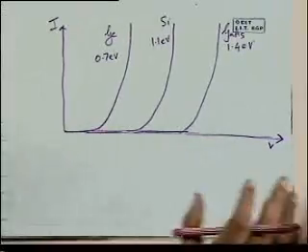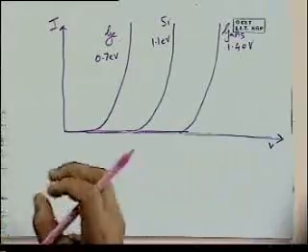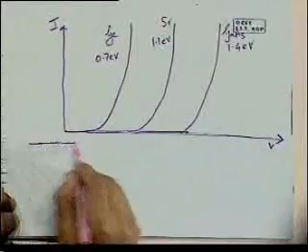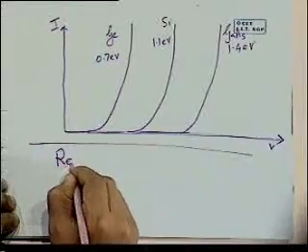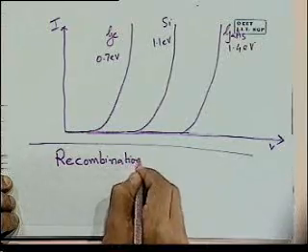So this is what we have written as a term for the current flowing under forward bias conditions that accounts for the diffusion of species under the lowered barrier. But there's another current term also that is related to recombination within the space charge layer or the depletion layer.